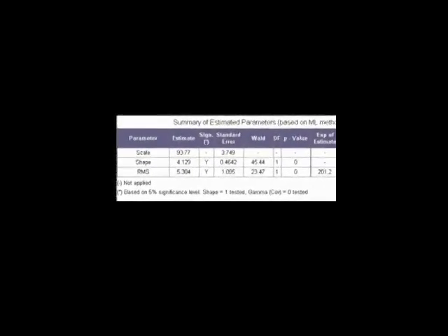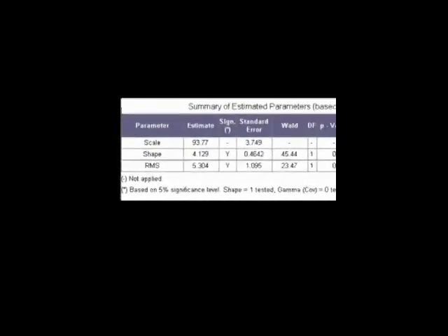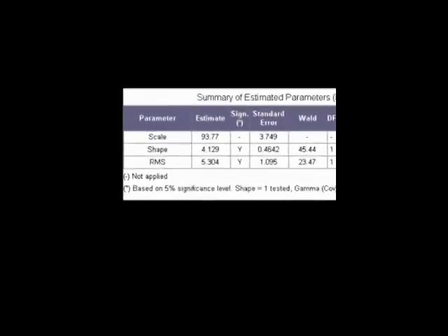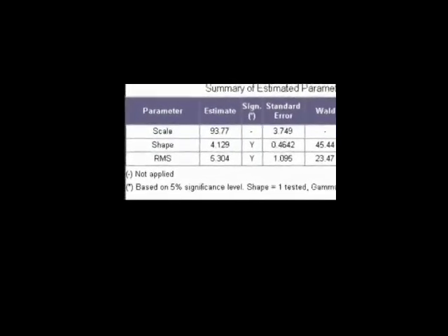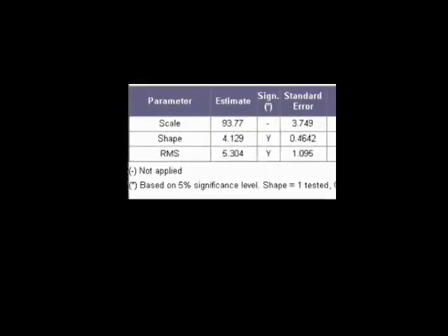Proportional hazard modeling has determined that the RMS vibration level is a significant variable. It has also determined that the shape parameter is significant. This means, regarding this failure mode, the working age of the component influences the asset's probability of failure. Hence, the decision model will incorporate both these factors.